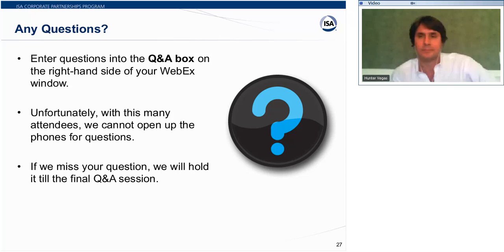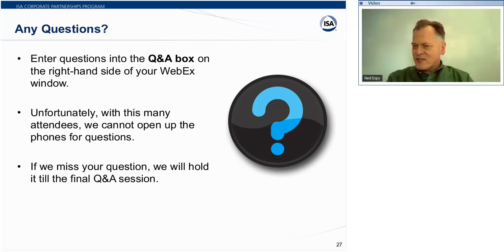Okay, next question. Coming to the calibration device, what is happening inside and is getting calibrated? I'll try to answer that one. I'm not quite sure what you mean on that, but if you're talking about the calibrator that Roy used, Roy showed that pump, and he's running a hose from the pump to the transmitter and the calibrator. So when he changes the pressure with that knob, the calibrator feels it, and so does the transmitter.